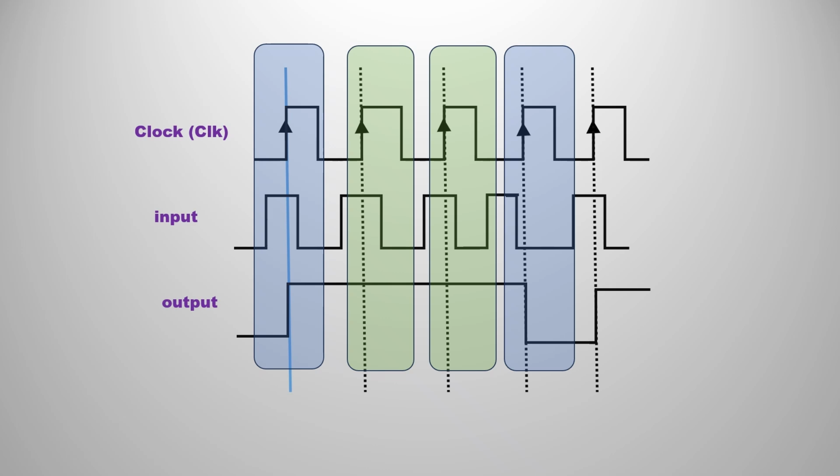If you don't understand even, you can also observe or relate with this here. At the same time you are going to observe clock, input and output so that you can get a relation. When the rising edge comes, we follow the input to produce the output. So input is rising, so output is also rising there, means high level we can say. Simply compare all of them, and near the fourth clock pulse the edge is high but the input is low, so the output is low.